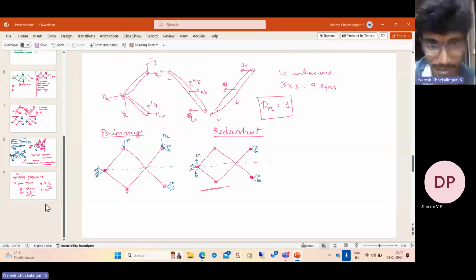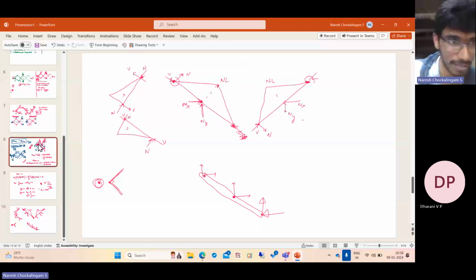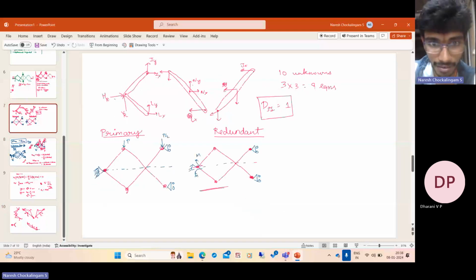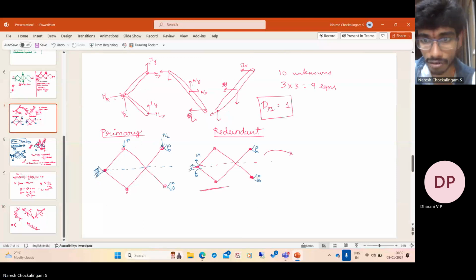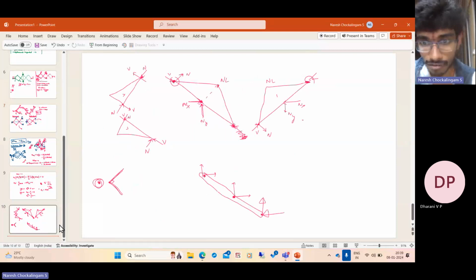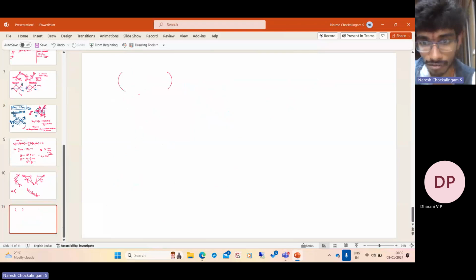Okay, I think so. This redundant structure is statically determinate. You can enforce this M, and reactions, and get the bending moment diagram. So from this you find out the bending moments of all members. Again, from this you can solve for the bending moments of all. Then you use Castigliano's theorem. So superpose both. Superpose whatever bending moments you're getting. So make a list of members.